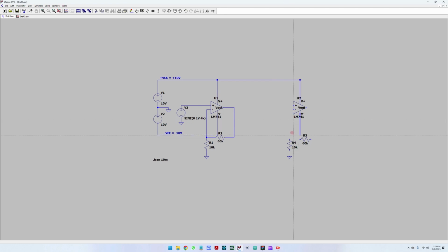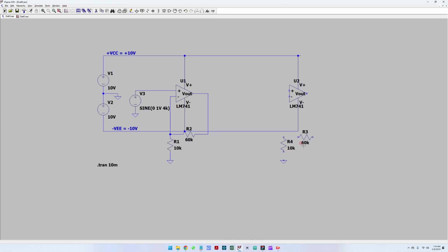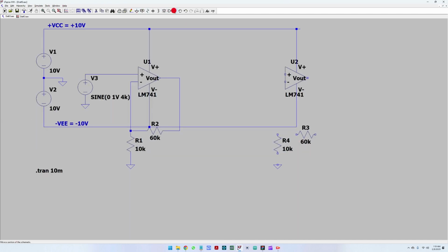We don't want to accidentally connect the minus to the feedback network. Okay, and now let's move these a bit lower because these are the feedback resistors, and we are great. One last thing, I'm going to copy the sine wave input and I'm going to place it here.